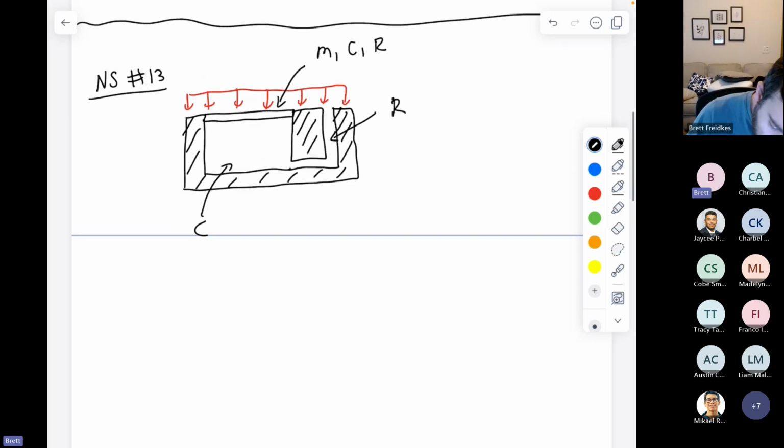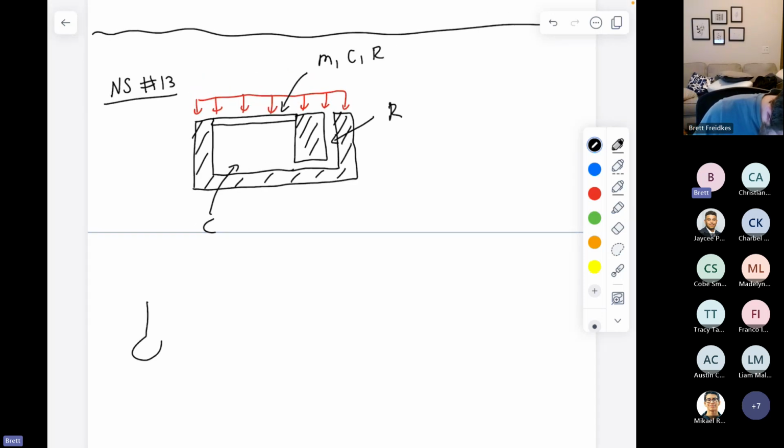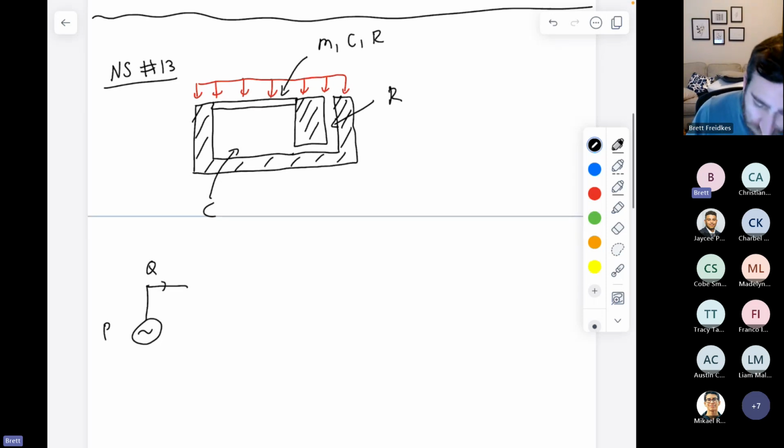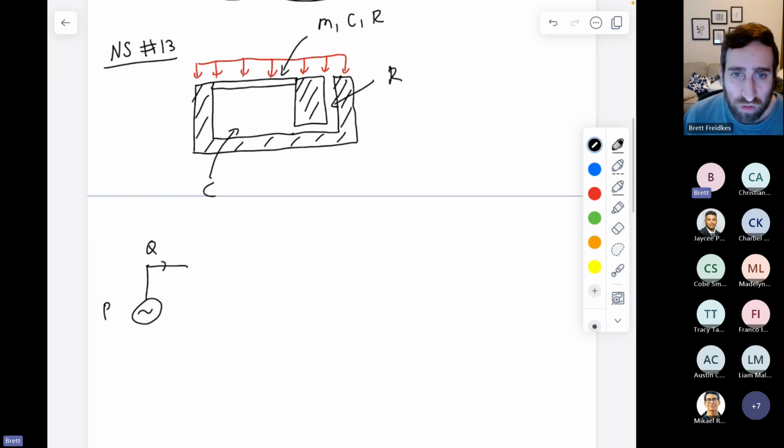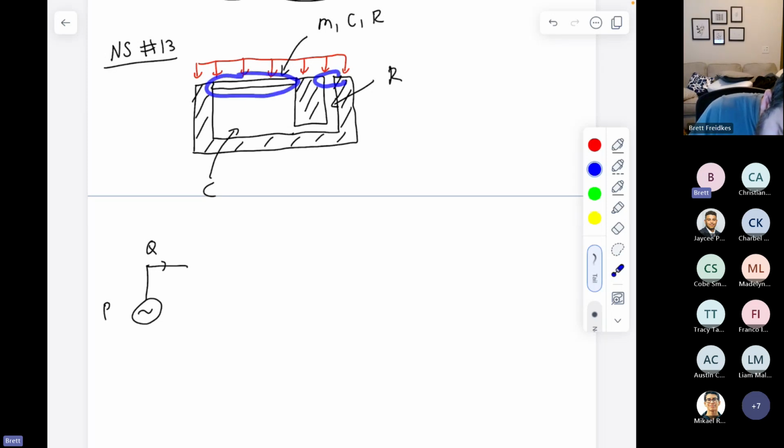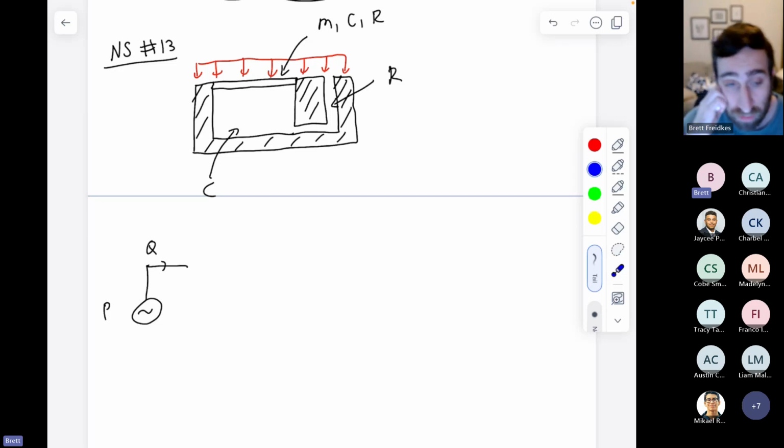And the circuit that we drew for LEM was to say we had this pressure signal that produces some volume velocity or has some volume velocity associated with it. And it was our job to figure out how things behave. So this volume velocity acts on the diaphragm and the vent simultaneously, which ended up leading to them being in parallel.